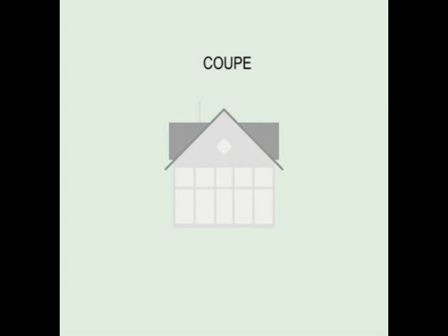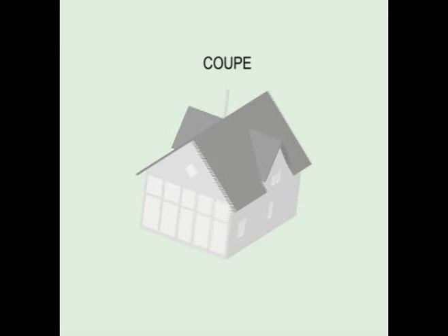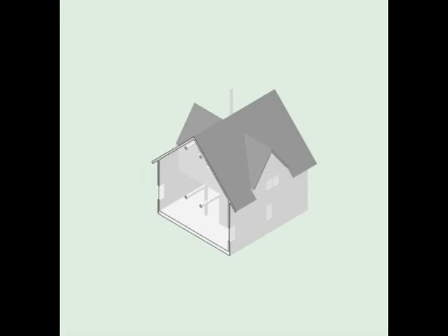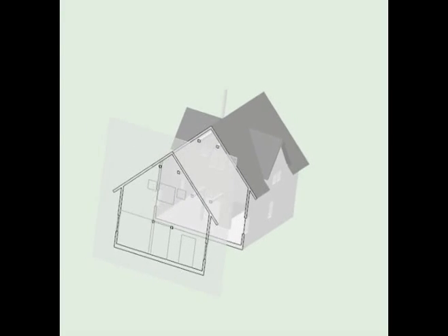To project a building section, first make a vertical cut through the entire structure. After a vertical plane slices through the construction, remove one of the parts. The building section is an orthographic projection of the portion that remains, cast onto a picture plane parallel to the plane of the incision. This cut opens up a building's interior to reveal the vertical dimensions and arrangement of spaces.